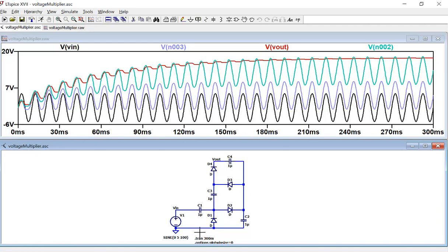So if you look at the circuit, this structure will shift the AC up. However, remember this part. In the first stage, the lowest DC voltage here will be 0 volts, right? We just talked about that, because whenever this is lower than 0, the ground is going to dump current into this node and make it 0 again.